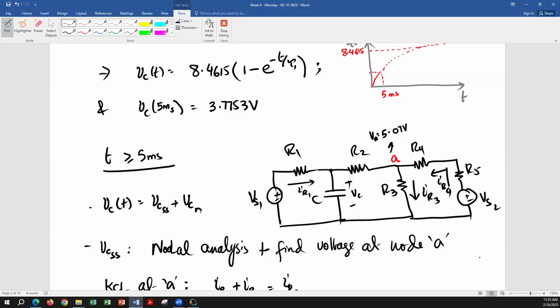The second way to do it, you keep that time, t is equal to 5 millisecond, but when you put e to the power negative t over tau, you put down e to the power negative t minus 5 millisecond over tau. So you don't shift the reference, but you take that 5 millisecond, subtract it from the actual time, and then divide by whatever the tau 2 value is. Whichever way you go is going to give you the correct result.